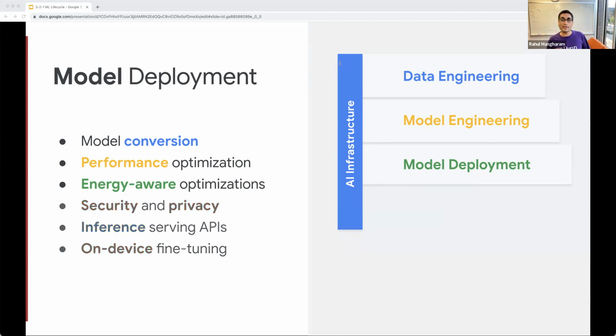And then you've got to evaluate its performance capabilities. Does it meet the real-time requirement you need? If I say, hey, Siri, and then it takes like 3 seconds, how do we optimize for latency versus model size? Then you're putting these things onto a small microcontroller running on a battery. So you've got to be very conscious about energy. And what does that mean in terms of optimizing for performance? It might not actually give you the best energy efficiency.